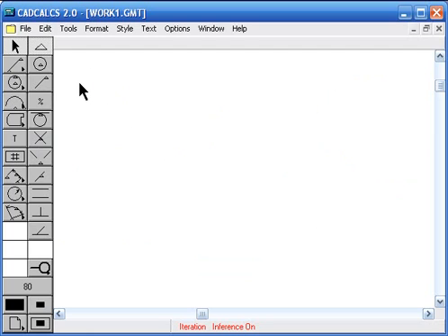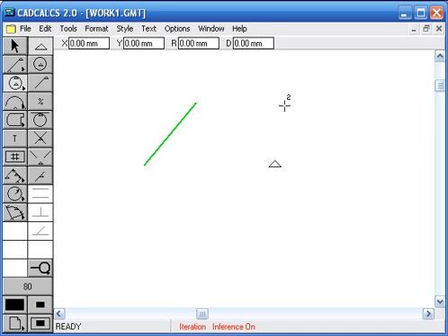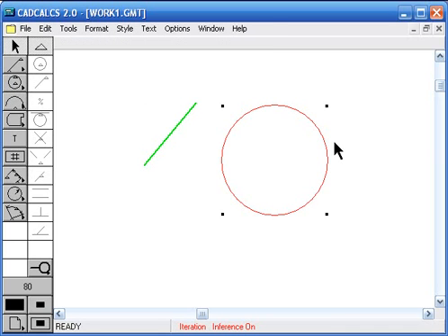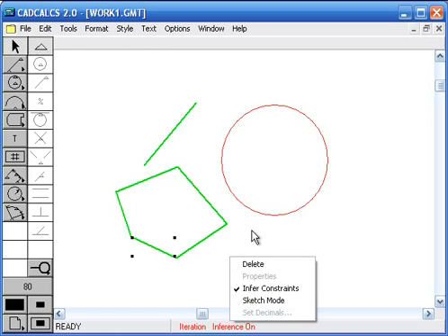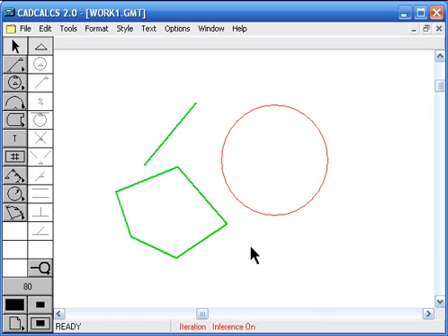To perform a single operation on a tool, you just click on the tool and then you bring your cursor in and you can create the geometry. For example, this is creating the 2-point circle. Here I can create a closed polygon. Just at the last point, click the right mouse button and it'll close the polygon. So for single operation, just click on the tool and follow the prompts.